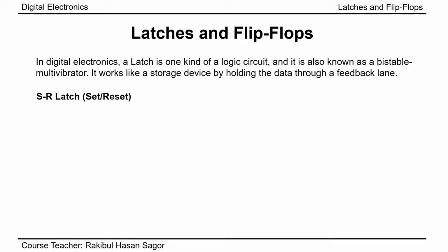SR stands for set and reset. We'll design our SR latch using NOR gates. Let me tell you the function of a NOR gate. We know that in a NOR gate, if one of the inputs is 1, we do not care about the other input. The definite output will be 0. It's for sure.